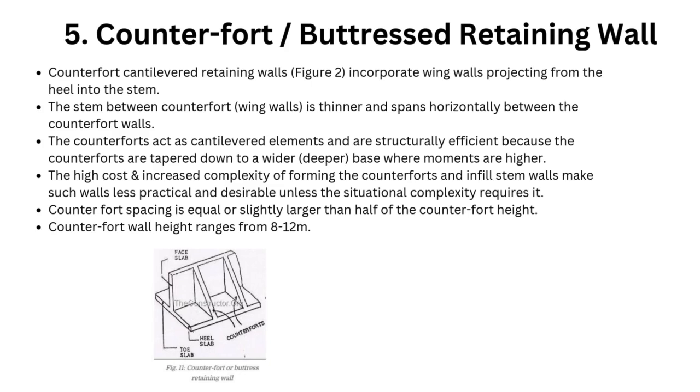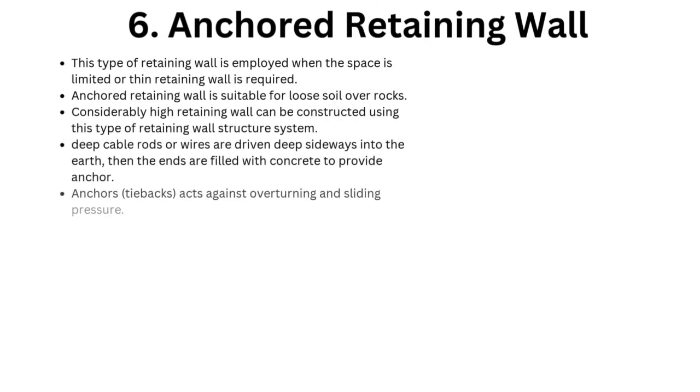The high cost and increased complexity of forming the counterforts and infill stem walls make such walls less practical and desirable unless the situational complexity requires it. Counterfort spacing is equal or slightly larger than half of the counterfort height. Counterfort wall height ranges from 8-12 m.